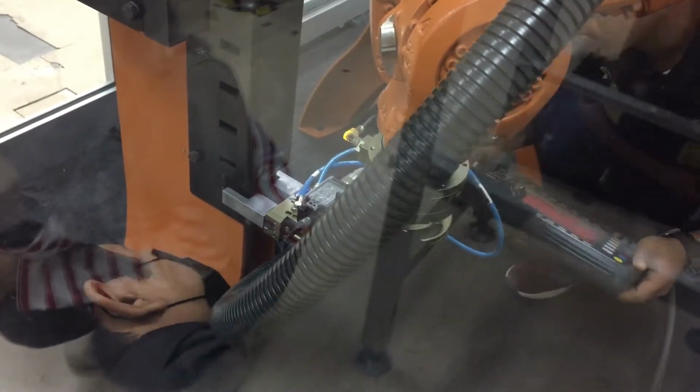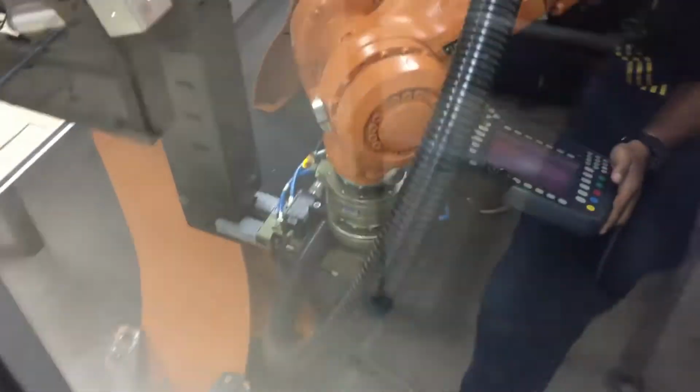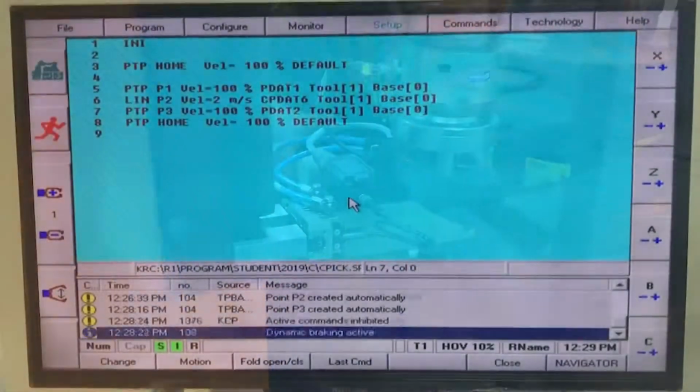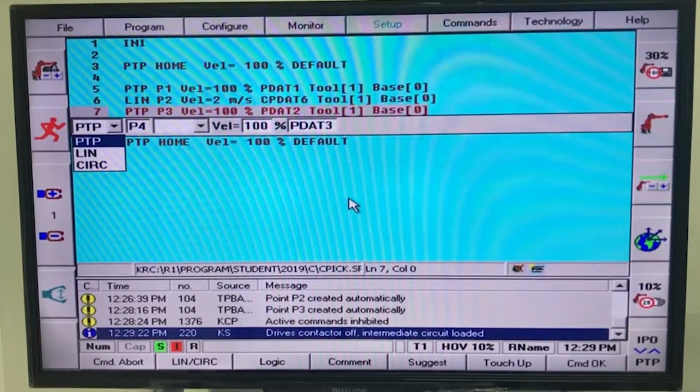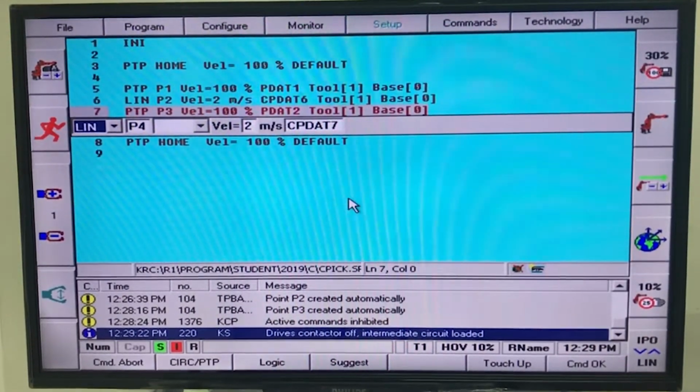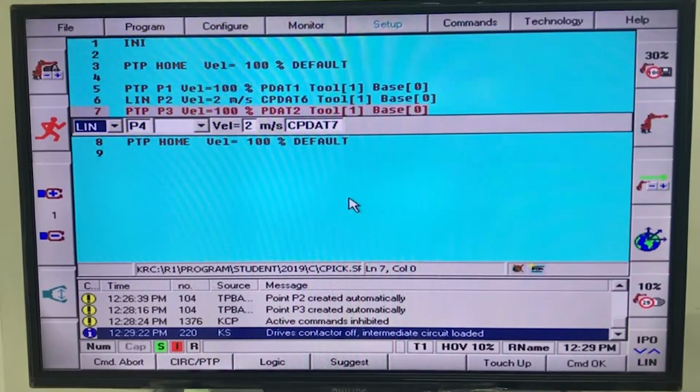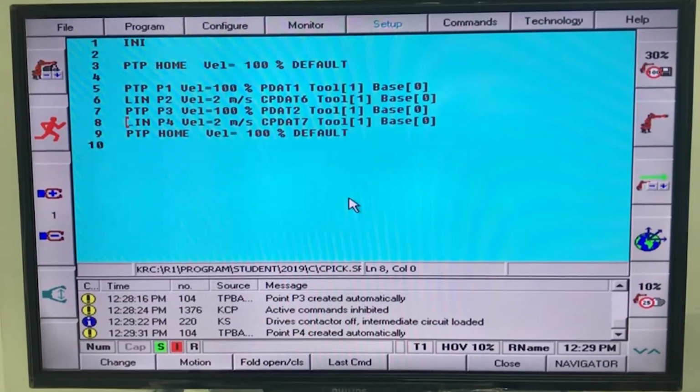Notice that the block is right in front of the gripper. The TCP is brought closer to the magazine using linear motion. Make sure that the block can be fully enclosed by the gripper jaw. A wait time of 2 seconds is created.